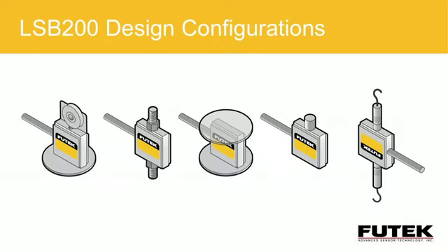We've designed it with a high flex cable with a spring strain relief because in most of our automation applications we're under constant movement. We're also introducing minimal mass to the system. This load cell is a very light product, and therefore the additional mass of the load cell to the system is significantly low, thus reducing the unwanted moment in the application.